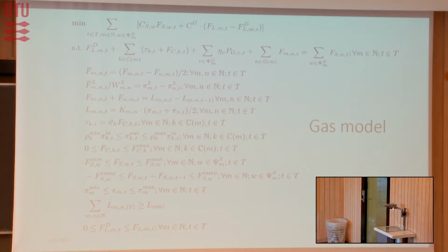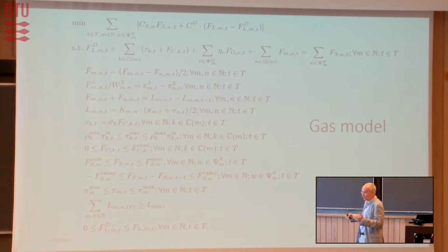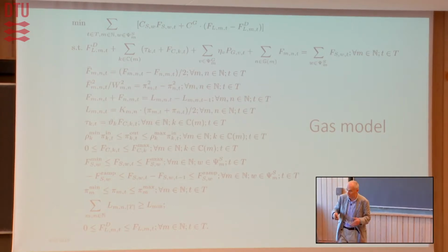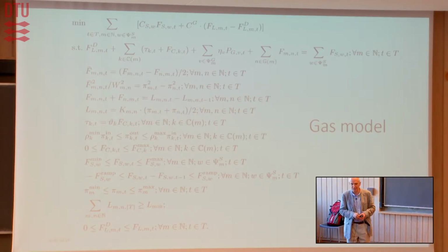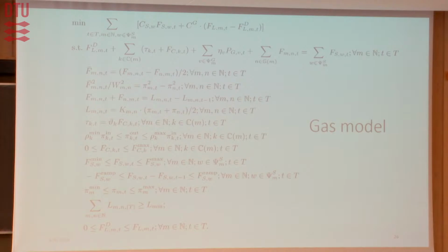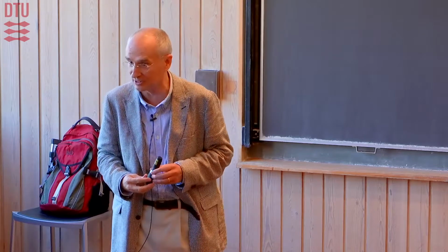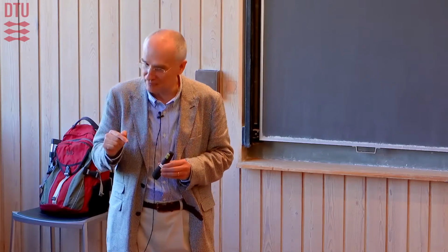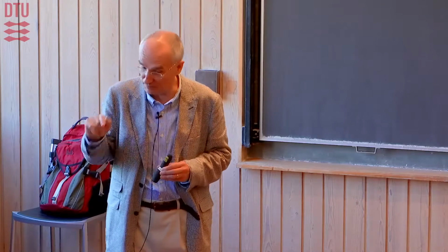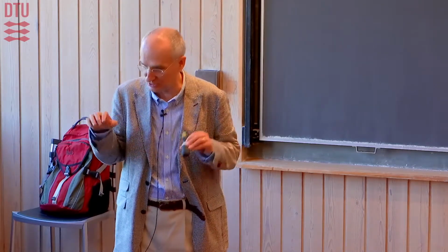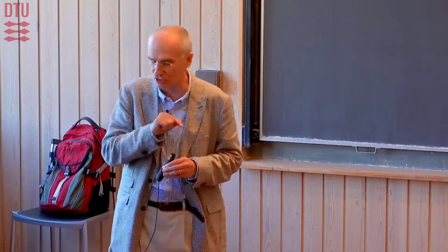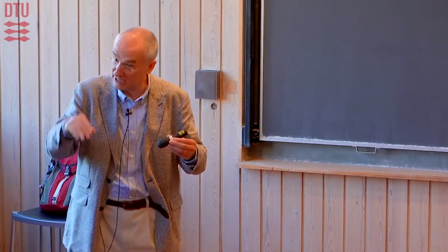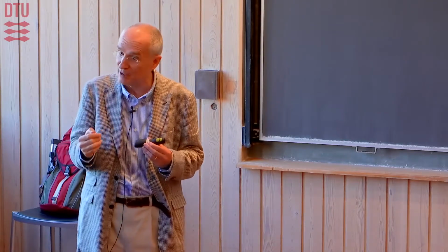And your experience? My experience, not for this equilibrium problem, but for a joint problem in which we solve jointly a unit commitment with all the description of the gas system, is that we convexified and looked at the infeasibilities, because the objective function is not that relevant. The relevant part is the feasibility we want to implement. With just the relaxation, you get significant infeasibilities. Then you build McCormick envelopes, and because they are local, you have to use a solution to build the McCormick envelope. You solve the problem again with it and get a better solution, but still with some infeasibility.